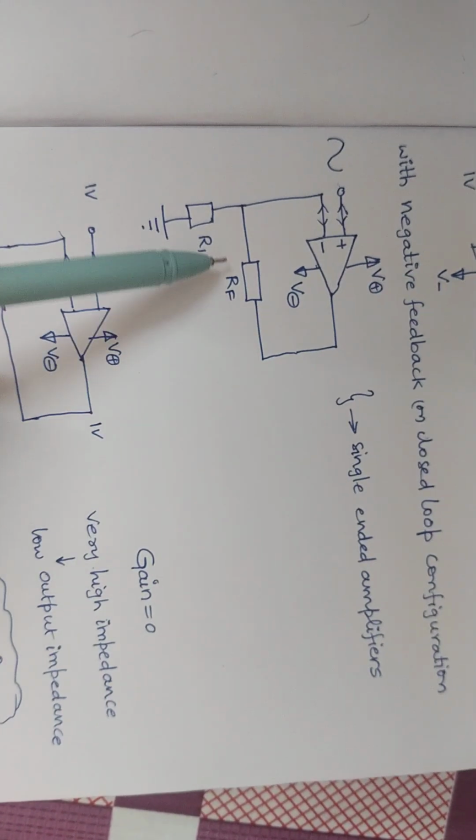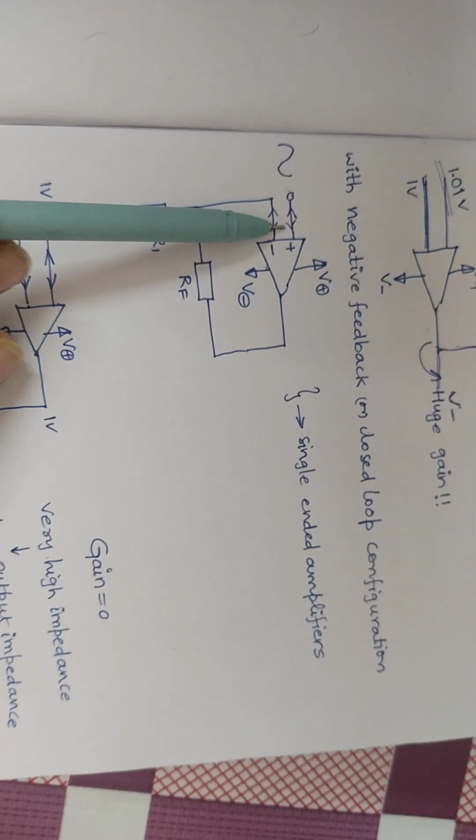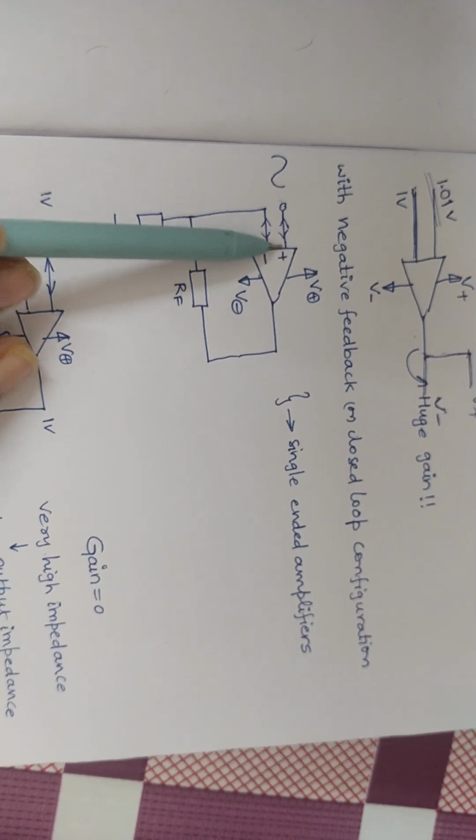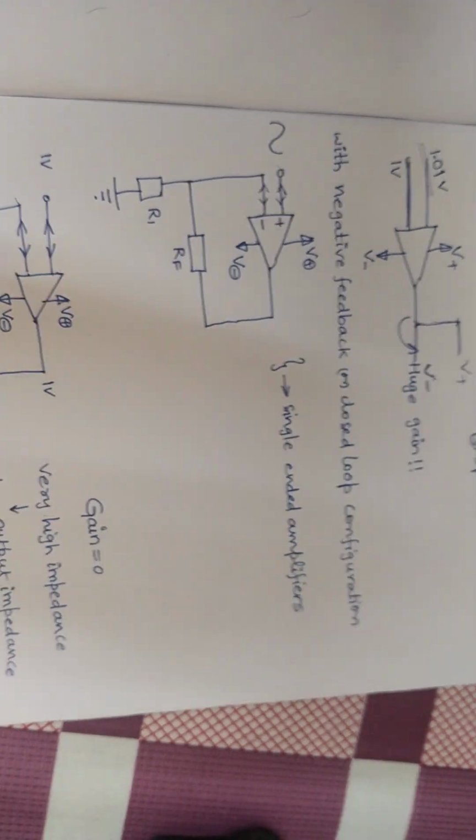So the need for it is the negative feedback. It can make the inverting terminal voltage the same as the non-inverting voltage through the negative feedback, not on its own.